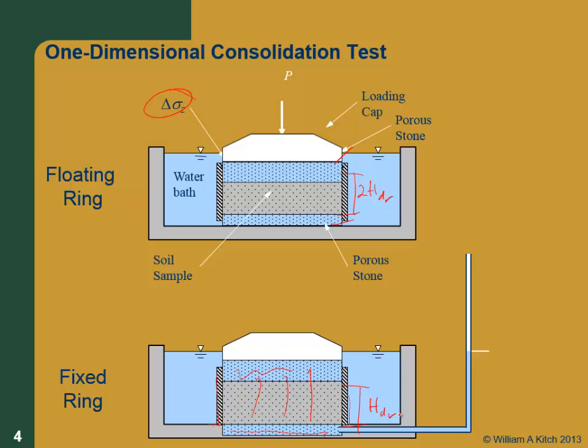The advantage of this method is that you can actually measure the pore pressures at the bottom of it. You can either measure them with a transducer, or you can measure them with a little standpipe. I just said all the flow goes out the top, but if you've got a standpipe, some of the flow goes out the standpipe, but you can make the diameter small enough that it's not significant. But most of this is done by putting a transducer at the bottom these days.